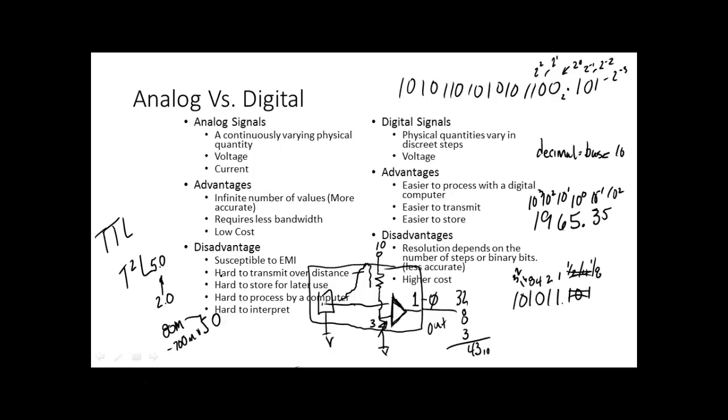There's a method called RS-232, which accepts anything from a minus 3 volts all the way up to a minus 17 volts. It accepts this as a logic 1. And anything between a plus 3 and a plus 17, it accepts it as a logic 0. So this was kind of strange when I got into this, because usually the negative, you think that's going to be the 0, but for some reason RS-232, they chose the negative to equal 1. So now, good gracious, I can run this thing off of almost anything and send it long distances.